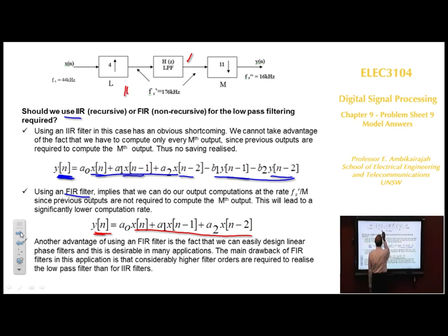So if you have 1000 samples here, naturally you would have 1000 here, but you don't need to calculate all the 1000, because you have to downsample by 11. You calculate the first one, 11 samples out, and calculate the next one, 11 out, then the next one. So you only have to calculate the samples that you need.